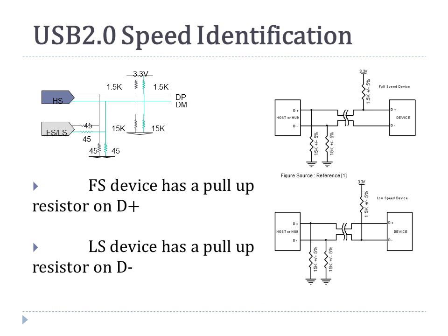Okay, as we discussed, it's kind of amazing that in USB various speed devices can get connected to the same socket, the same USB receptacle. So there has to be a way by which the USB system identifies the speed of the device when it gets connected. To help identify the speed of the device, the low speed and full speed devices have a pull-up